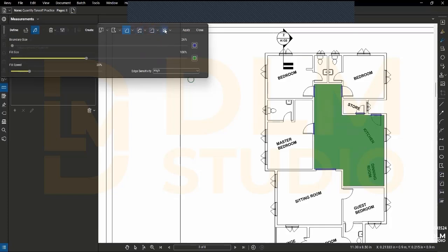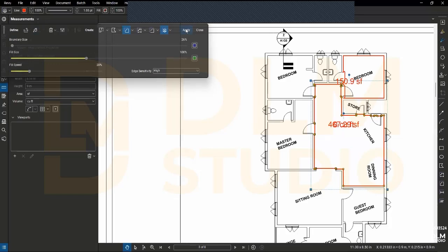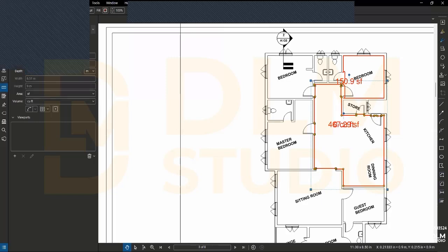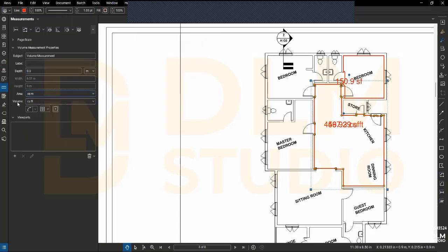It's how to measure volume of lateral filling from just that part. Just click on this volume. Once I have that, I just close. The thickness should be 0.0. Area, square meter, volume, cubic meter. See all of this overlapping.